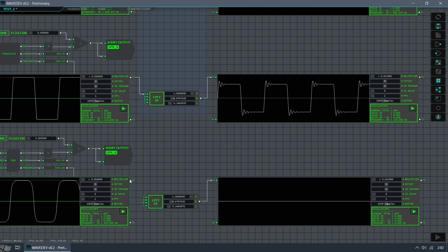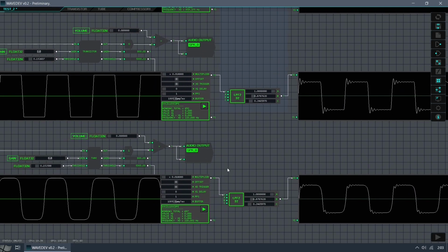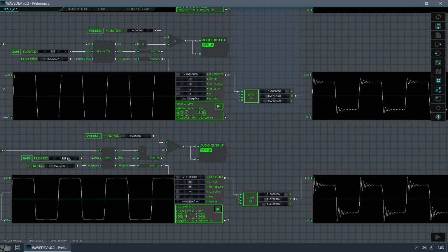If we apply resonance to the output of the tube, the oscillation is smaller, due to the soft clipping. So the coloration would no longer be as intense as this one. Although this does not mean that we cannot achieve this coloration with a tube. We could simply continue increasing the gain until reaching equivalence to the transistor. But as you know, increasing the gain too much has some drawbacks. I'm almost doubling the gain compared with the transistor to get the same spectrum.